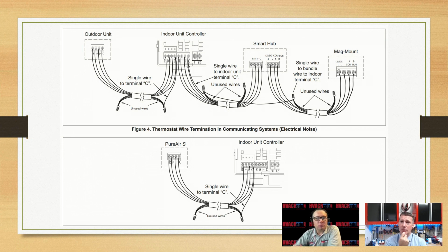Exactly. Anyway, those wire nuts, for anybody who wants to tell us what's going on there, looks like it's all going back to the indoor unit. Why would we do that? And then trace it down, you go to the outdoor unit, but hey, those extra or unused wires are not hooked up to anything, but they go back to a common. Everything's going back to common at the indoor unit. Sounds like some kind of grounding to me.